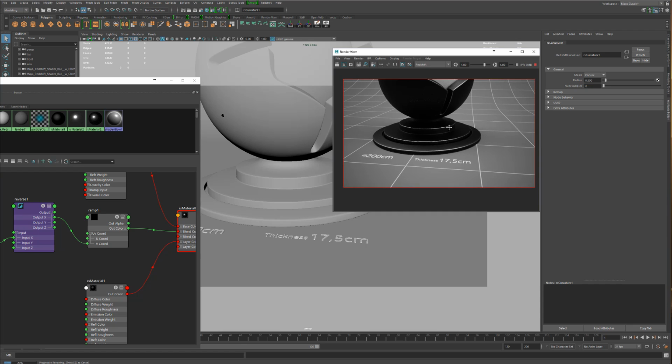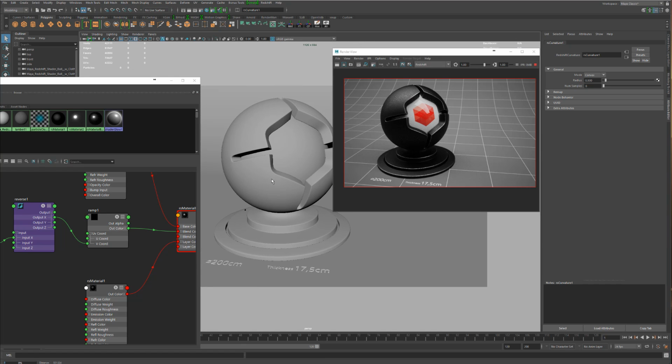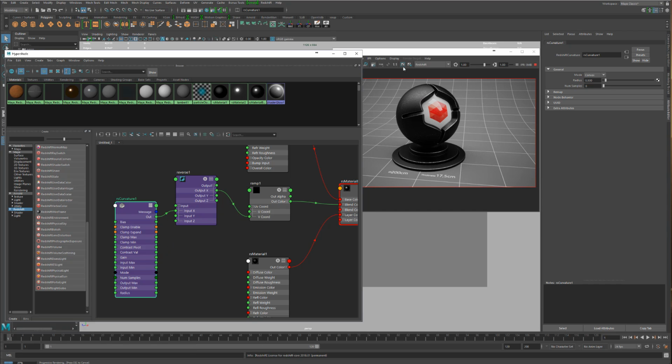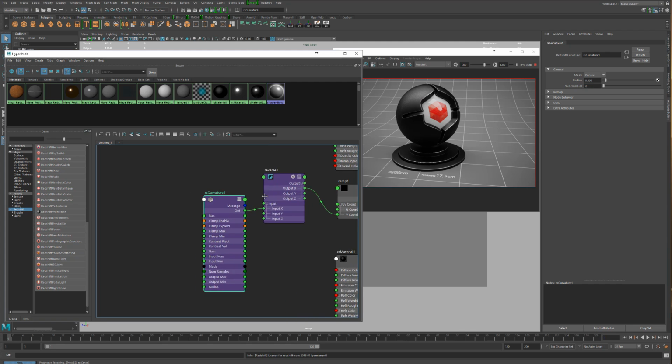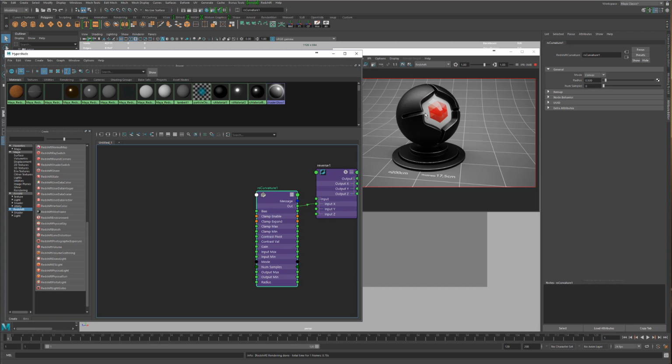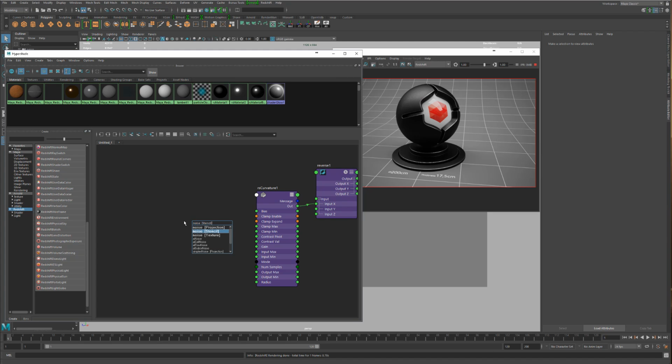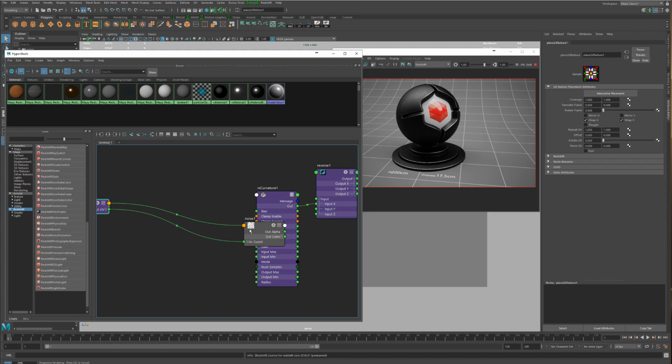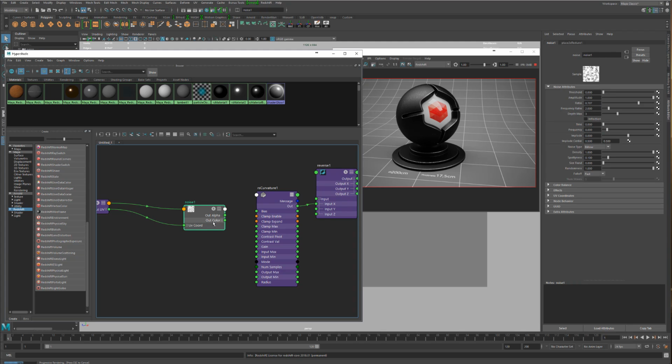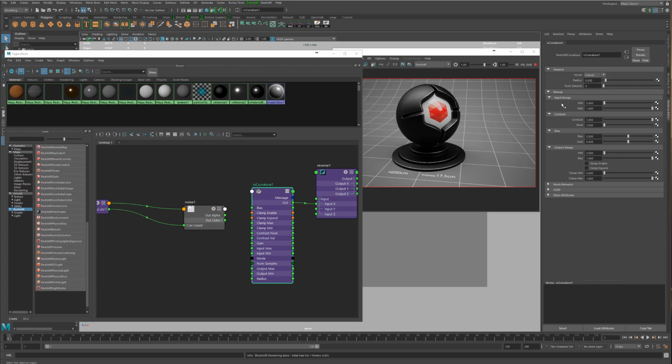So let's zoom out of this. Now that we've got that going, right now it's very clean. To add a little noise to the convex scratches that we're going to add, we're going to feed this a noise. So we'll use a texture noise. With this, we could then tell the remap section of contrast, and we could feed it into this contrast slot. Let's put that into contrast value.